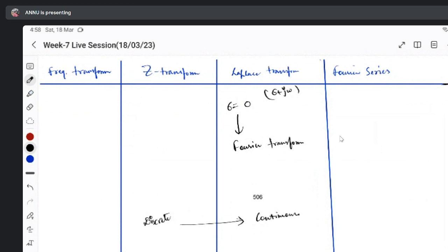Madam, it is true. Fourier transform is applicable only to finite energy signals, which is stable, right? Yeah, this one only I am trying to get the answer from you. Dirichlet conditions: finite energy, finite number of peaks, finite number of discontinuities. This is all about the Fourier transform, which is only applicable for a stable function and finite signals, which have finite energy, finite number of discontinuities, and finite number of maxima and minima also.